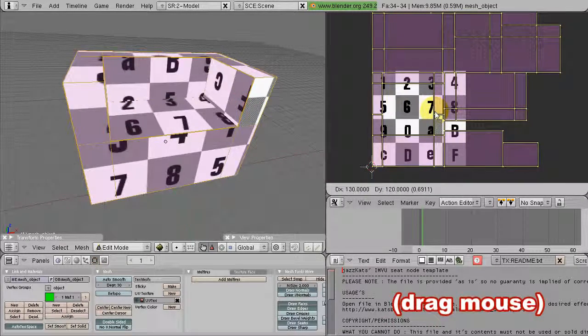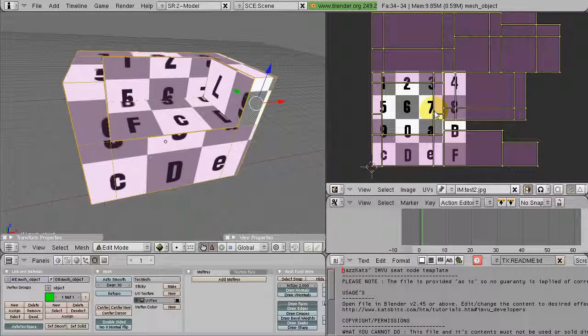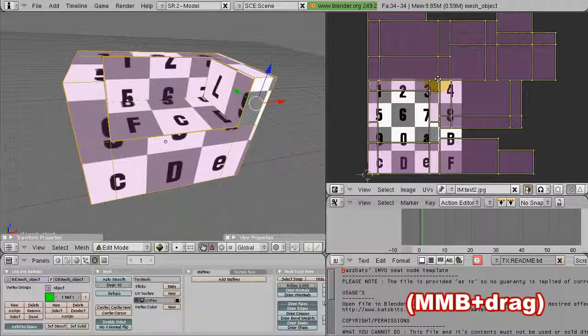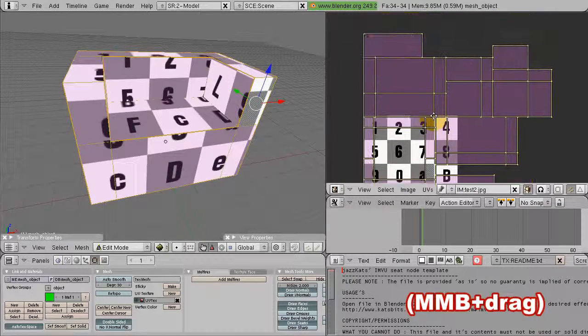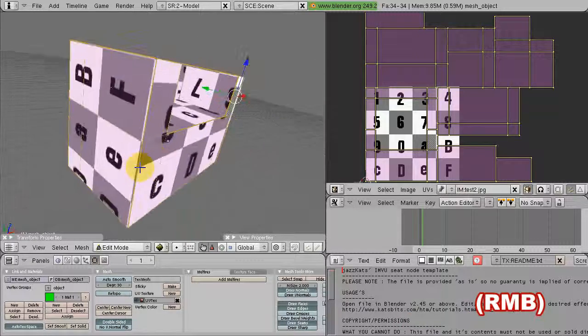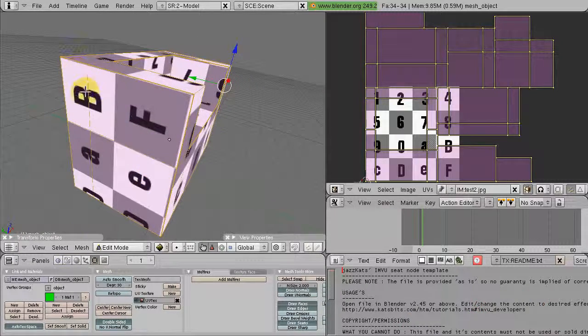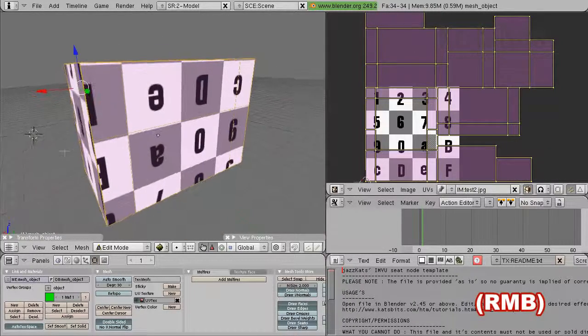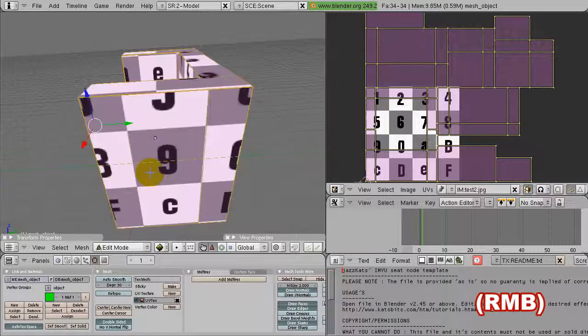around. In essence, because this is a tileable texture, we don't need to do much else with respect to the UV map's layout other than making sure all the little elements of the UV map are facing in the right direction. Because otherwise, if, for instance, this were a chair with a fabric texture applied to it that had a grain to the fabric, like corduroy, you'd want the UV map to be set up in such a way that, regardless of what you were looking at on the mesh, the grain was always facing in the right direction relative to the chair and the fabric.